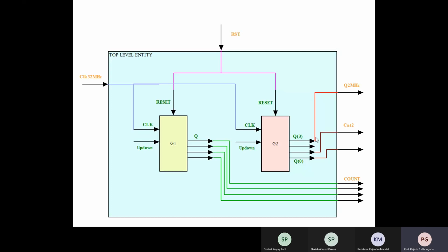Sir, after 8 clocks. Yes, in the 9th clock. See what is happening? This is a counter, and this counter is driven with a 32 megahertz signal, a clock. So when will Q1 change or assert, at what rate? Q0, when will this change?